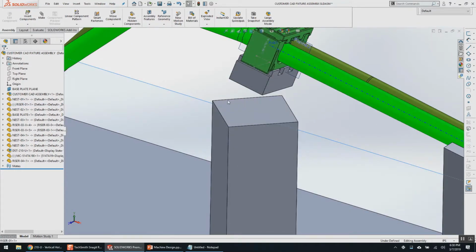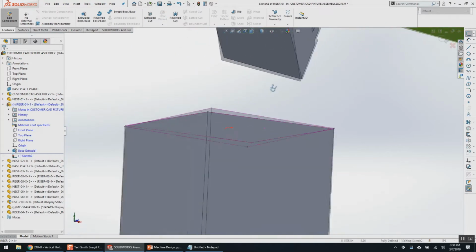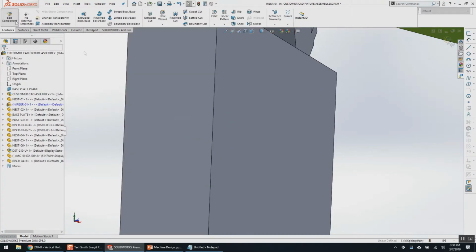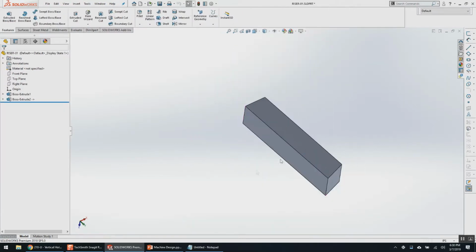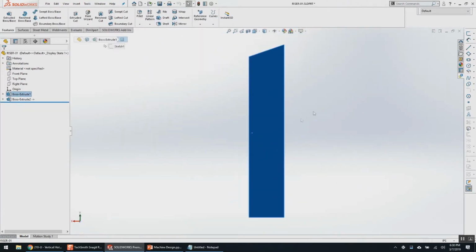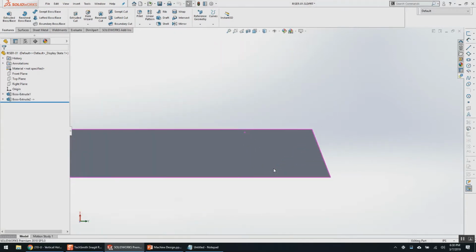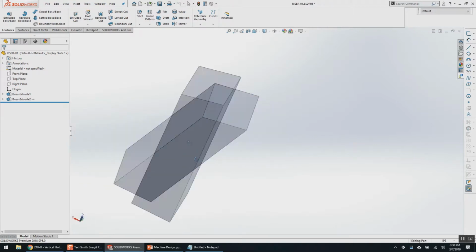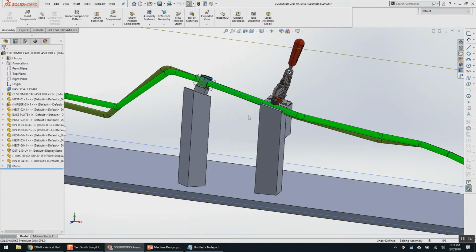Now when I'm making this particular block, this is going to be hackish and dirty, so I won't leave it like this, but here's the example. To take this block and put it in a vise, I can side mill that. I can side mill that pretty well, or put it on a right angle block and sign block it or whatever, right? And I can deck this pretty easily. A double compounded angle, and that would be very hard.